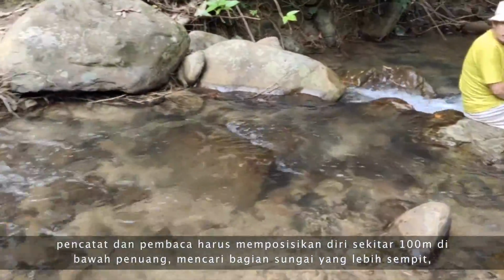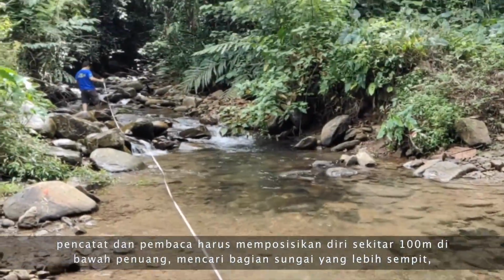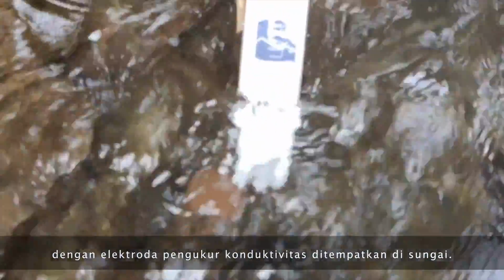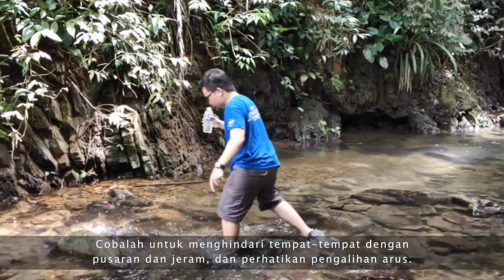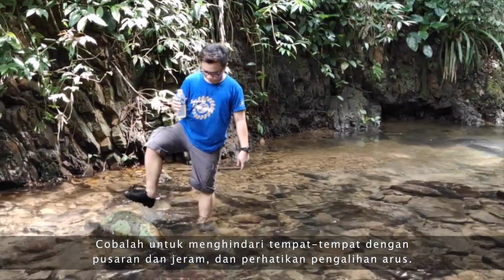The note-taker and reader should position themselves between 30 and 100 meters downstream of the pourer. They should also locate themselves in a narrower part of the river with the conductivity meter electrodes placed inside. Again, try to avoid places with eddies and rapids, and take note of stream diversions.